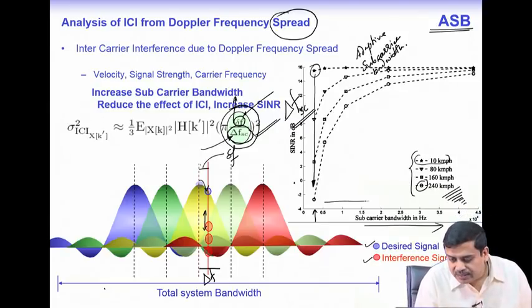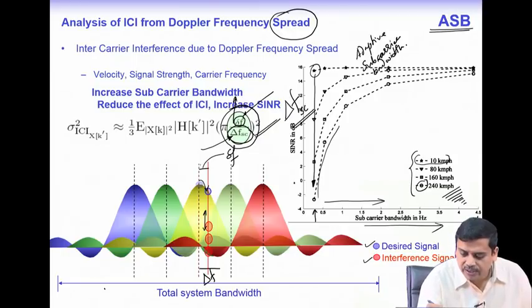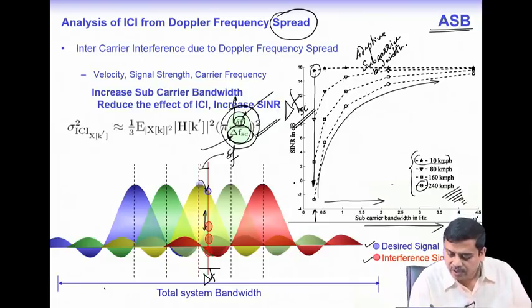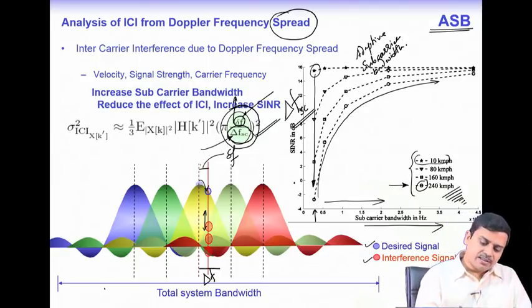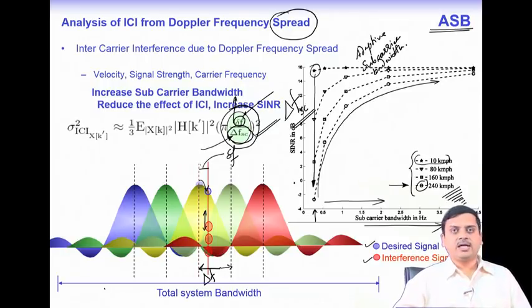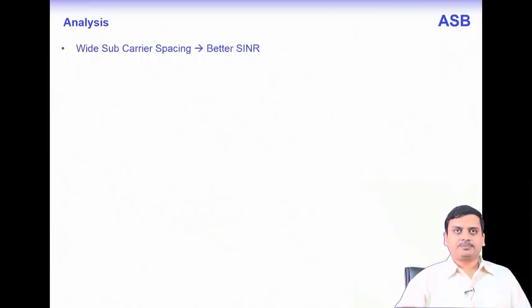As you increase the subcarrier spacing, the signal to interference ratio increases beautifully, especially for the ones with higher Doppler condition, right. So, this clearly indicates that to handle higher Doppler conditions, having a higher subcarrier bandwidth is a much better solution than implementing advanced interference cancellation techniques, which also get limited when you have multiple paths coming into play and there is a spread.